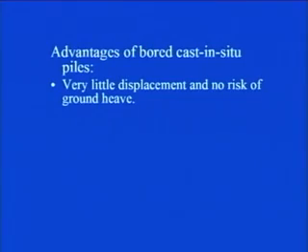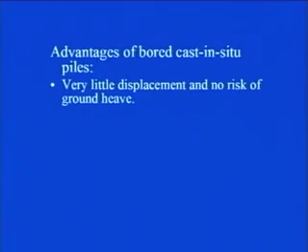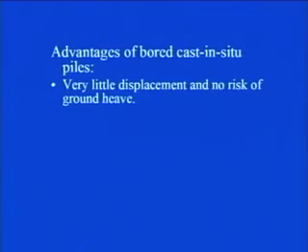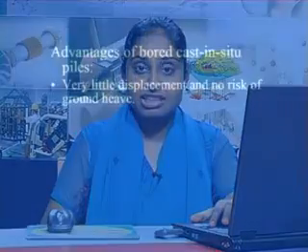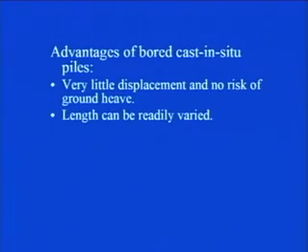Very little displacement or no risk of ground heave. As you know that this falls under the category of non-displacement piles. So, in this case, there is no mechanical hammering which is taking place while driving this kind of pile. So, very little displacement is there, and there is no risk of ground heave at all.